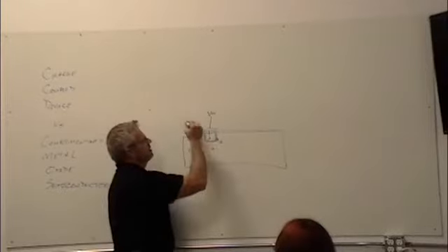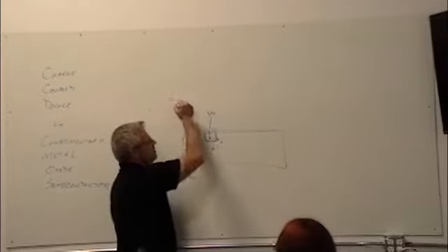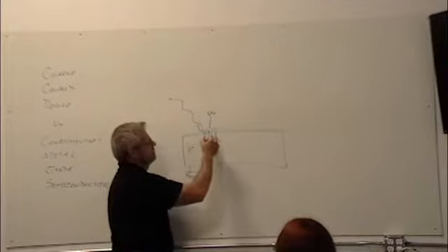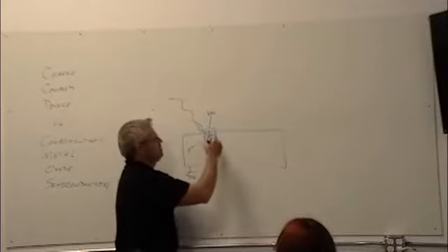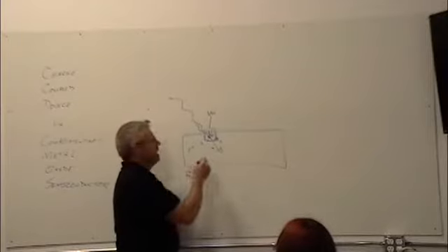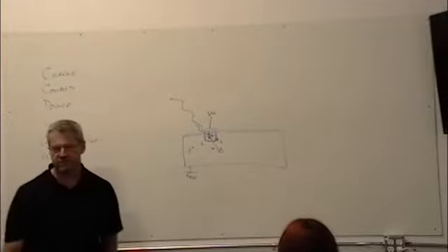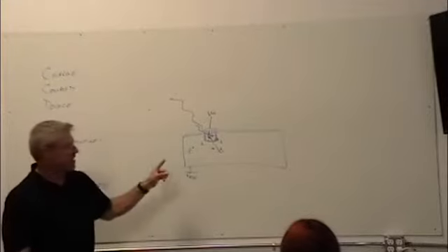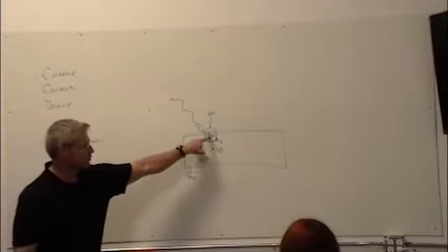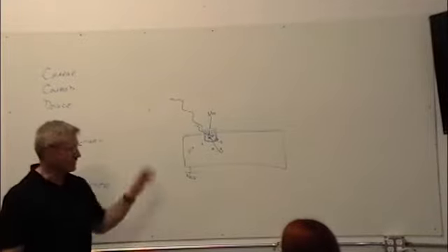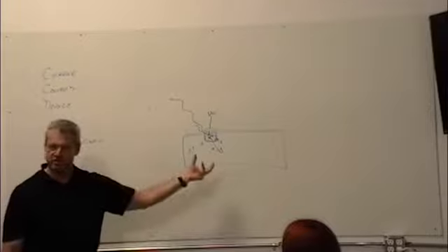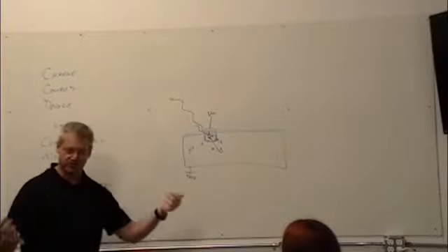If I have light come in and strike here, an electron-hole pair forms, and the hole is going to be immediately driven out. The electron is going to be pulled up towards the surface and is going to stay there on the surface. So one photon comes in, one electron is created. Another photon comes in, another electron. I say created, it's broken loose.